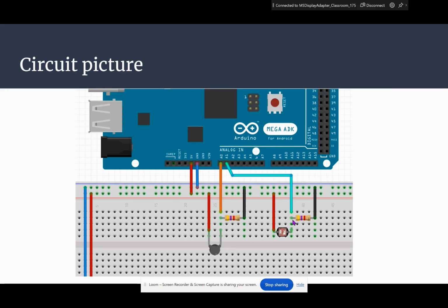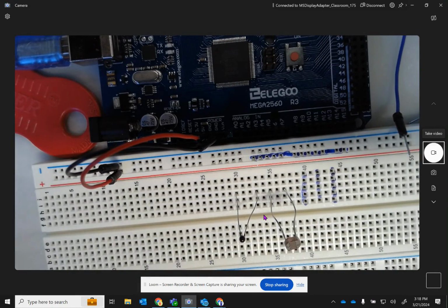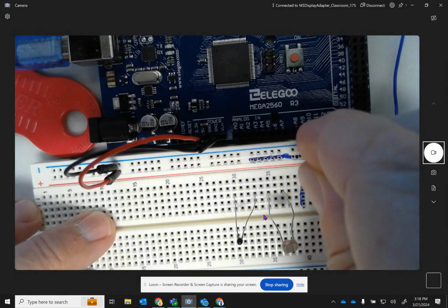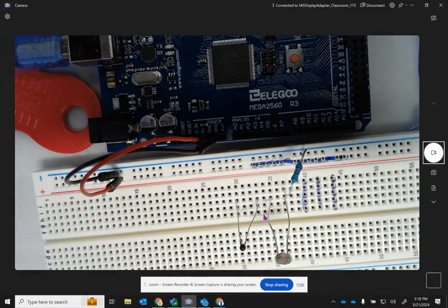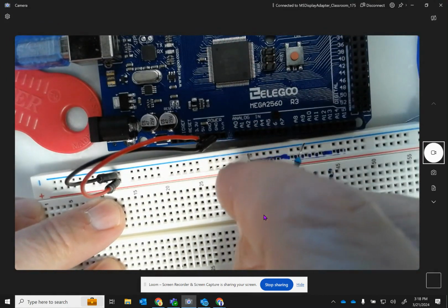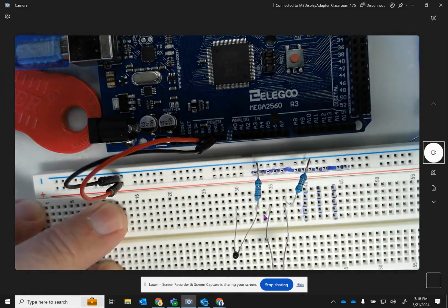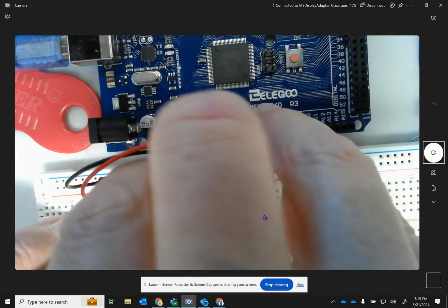And very similarly, that happens with the photocell, okay? So let me go ahead and hook that up real quick. You'll see that it's not terribly difficult. Let's see, we go ground to one side of the photocell. And we're going to go ground to one side of the thermistor. Okay. We are going to go this to power.